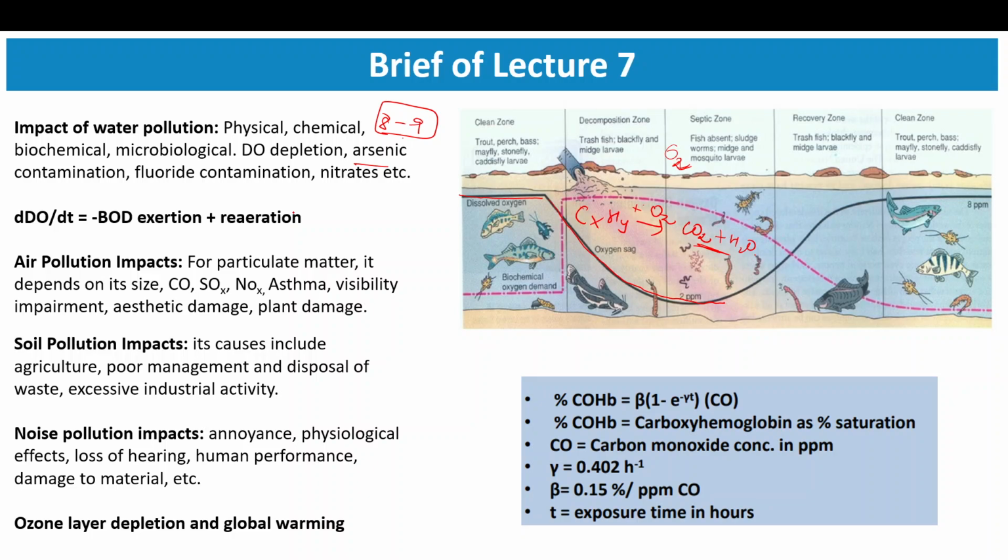Next, there could be excessive nitrates or nitrogen concentration. Nitrogen is an important component of fertilizer. You would have heard of NPK fertilizer, where N stands for nitrogen. Nitrogen is a nutrient in fertilizer for plants to grow, which we supply. Now, if there is excessive nitrogen available in water, there will be excessive growth of plants in the form of algae or seaweed.